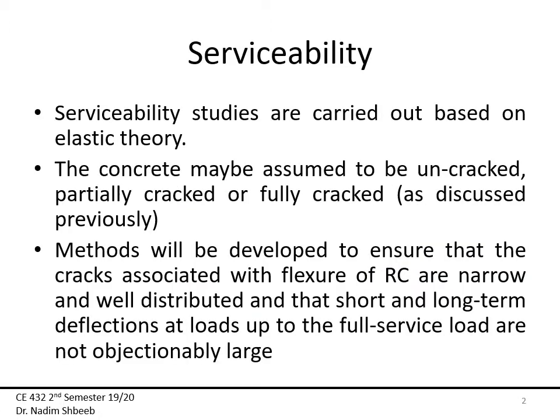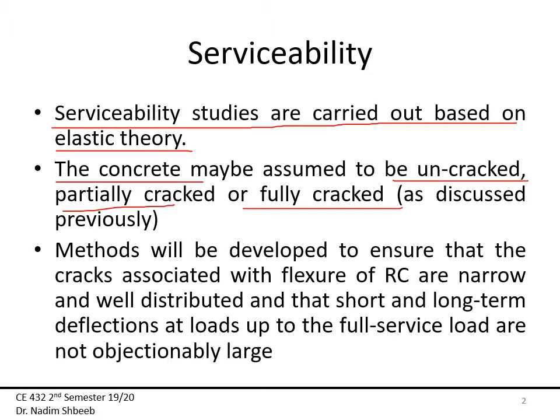Now, serviceability again, crack and deflection control. All the serviceability studies are carried out based on elastic theory. So Hooke's law applies. Stress is equal to E times epsilon strain. Concrete may be assumed to be uncracked, partially cracked, or fully cracked, and we had full discussions of that when we talked about the design for flexure back in chapter 3 of the text.